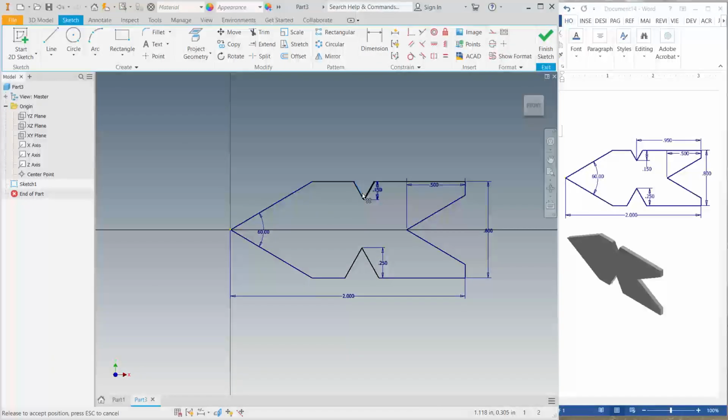So I can grab it. This means you need a location, you need the dimension in here. So I can press dimension, click on these two points, apply 0.95. And then same thing in here, I escape. I can move this triangle.